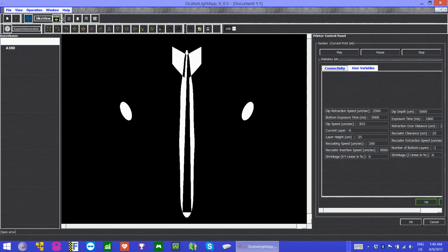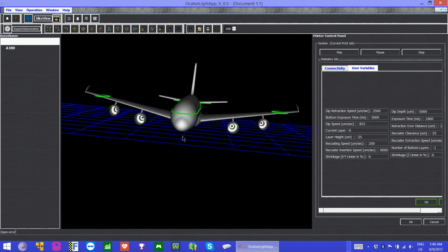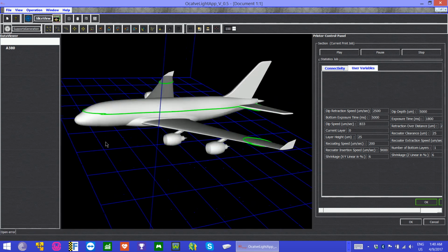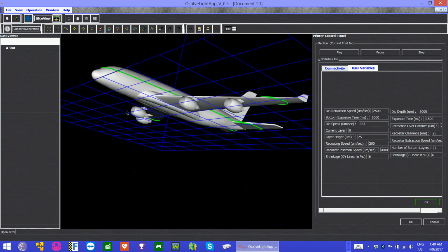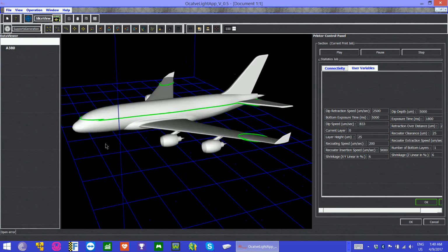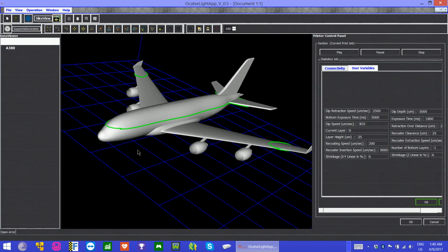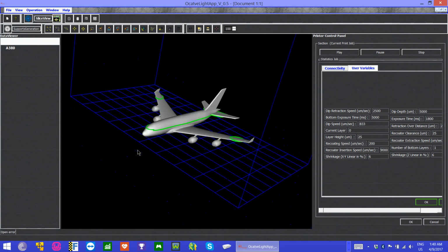And if you see the 3D view of the slice, you see which parts, the fuselage, wings, are coming in. This is a mathematical computation we do with the model: we put a section plane at that particular layer height, cut the whole model with the section, and extract the cross section all along the body parts.